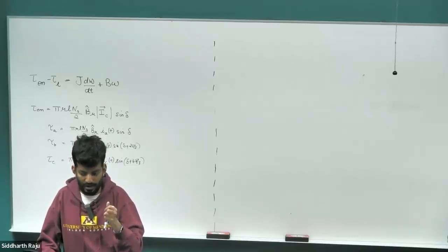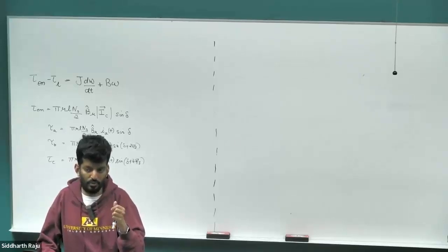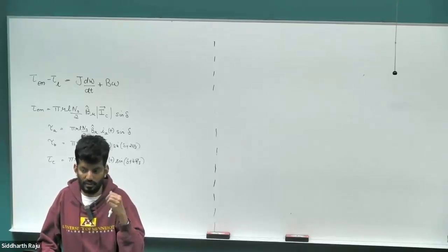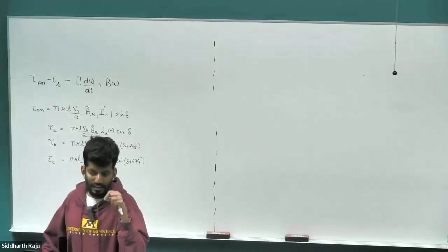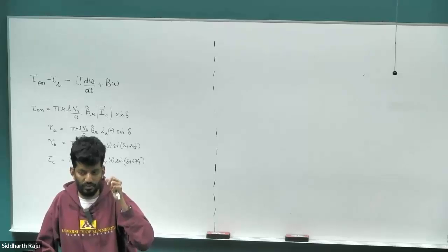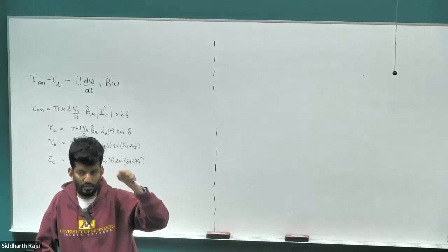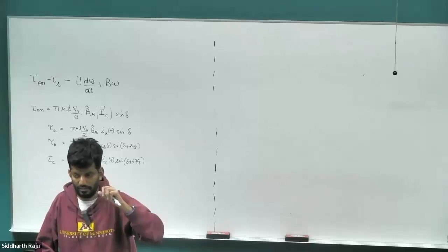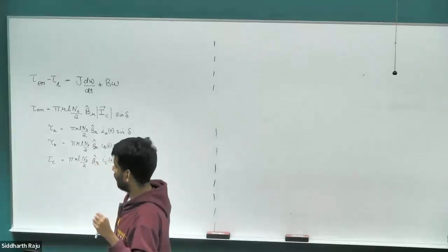So you put these aluminum bars and then you don't put any rotor magnets. In those cases, you would do one phase because you don't want to have the added cost of putting a 3-phase coil. You would use some tiny, very thin conductor to create an auxiliary secondary 2-phase system, which would shut off immediately after the rotor starts rotating, so that the coil doesn't burn out. It's a very thin copper wire. You don't want to waste money on it.